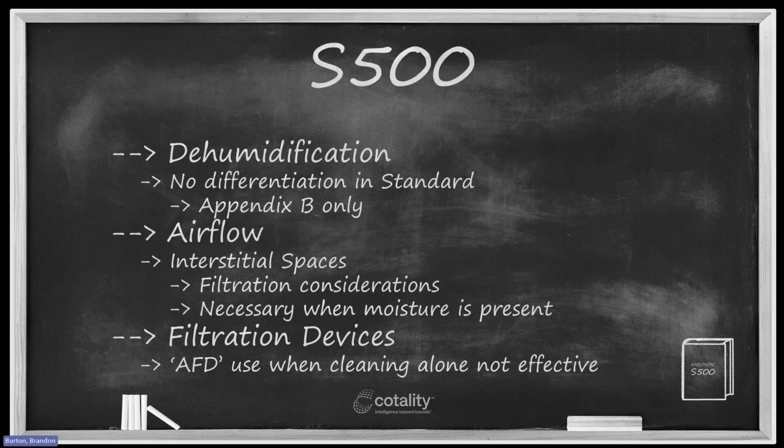And that is definitely a call out to specialty drying systems, because the only way to get air to move in an interstitial space or cavity is going to be through the use of either a specialty drying system or demolition, right? One of those two is going to have to happen. So we'll talk a little bit about what the S500 says about that as we dig in today. We'll also get specific into some of those specialty drying systems that deal with that for us.